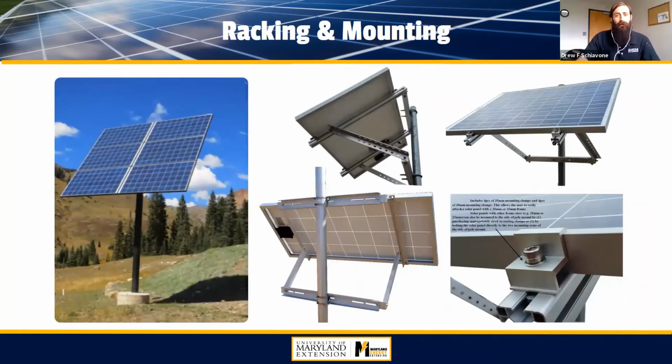We'll take a look at pole mounted systems here. And this is different because you're building from the foundation up, literally. You're not starting with an existing structure. You're typically putting a concrete footer in and then putting your metal pole. It could be 2 inches, 3 inches in diameter. Really depends on the setup you're going for. But off that pole, there's all kinds of mounting systems you can use.